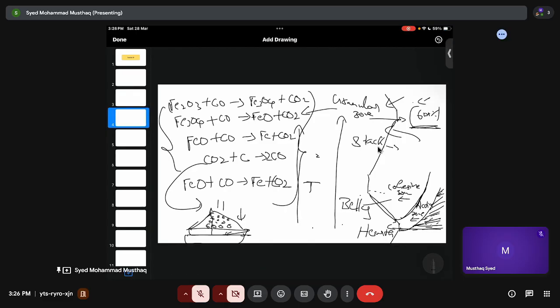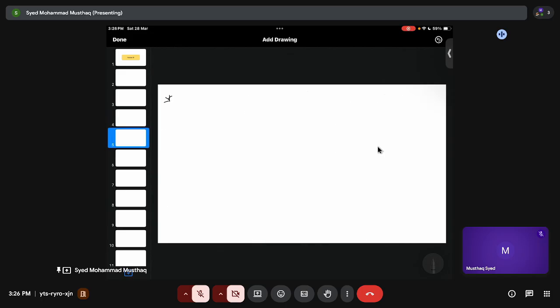And you have phosphorus pentoxide and other things going, right? These are the different types of impurities that you will find. Also carbon, because it is getting saturated, and because these are very highly reducing atmospheres, with the carbon monoxide and the temperature that we are using. Because of this highly reducing atmosphere, you will see the pickup, or the reduction, of these metal oxides also.